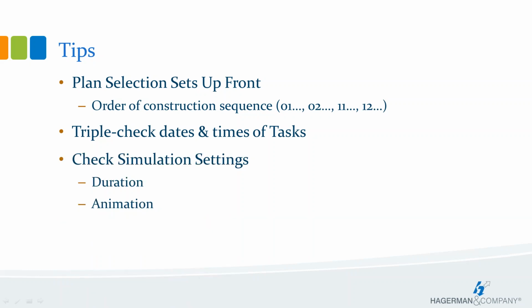And lastly, use the Animator for more control over what the camera is doing. It is possible to use a bunch of saved viewpoints here, but I think you'll find that trying to do an entire camera sequence by only using the viewpoints can be cumbersome. Remember in my example, I still used a viewpoint, but all I did was add it to the Animator and then let the Animator take over.